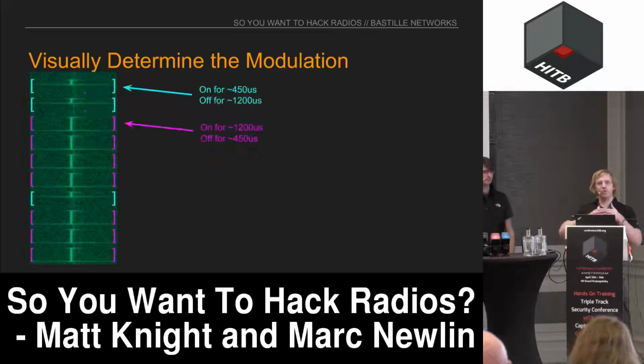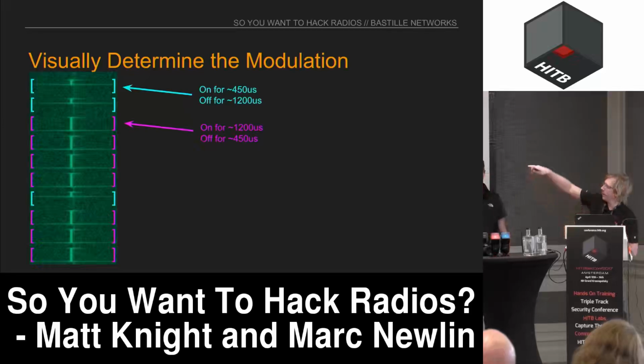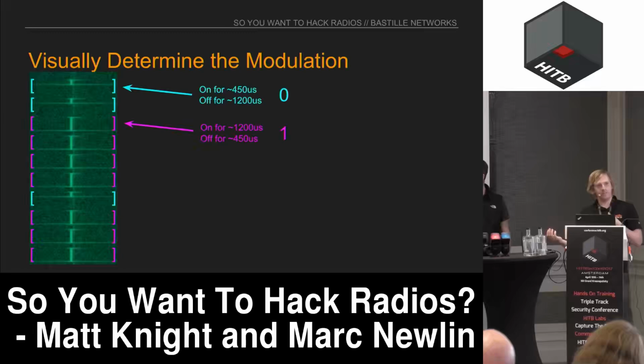And we can see that there are two different states. First, we have that top example of the transmitter being on for around 450 microseconds and then turning off for around 1200 microseconds. And then we also have the inverse of that, where the transmitter is on for 1200 microseconds and then off for around 450. So we can see that we have these two distinct things that are repeated. So we can infer that one of these is going to be a 0 and one will be a 1.